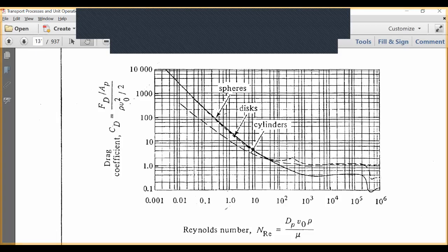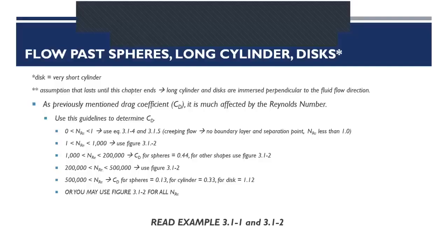You can try to find the drag coefficient using the Reynolds number. You can use figure 3.12 directly, or you can use these guidelines to determine the drag coefficient CD.